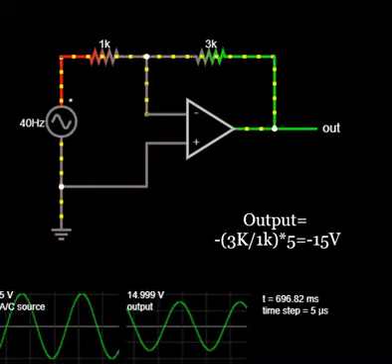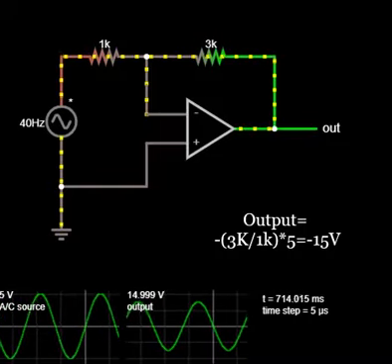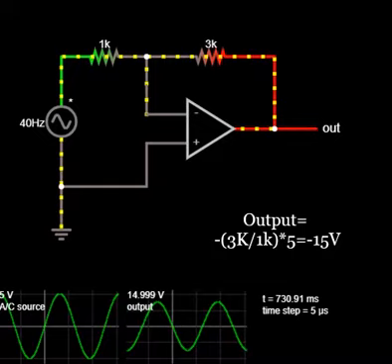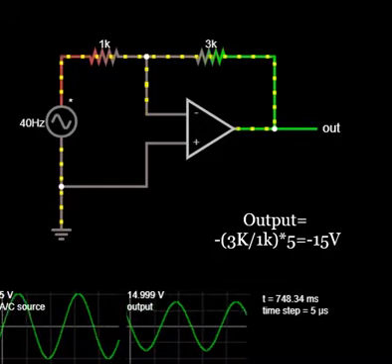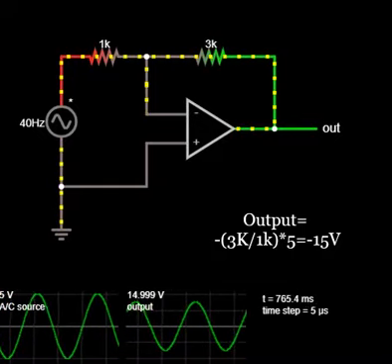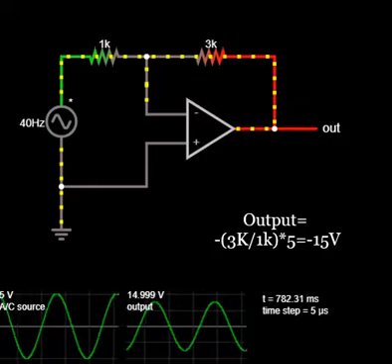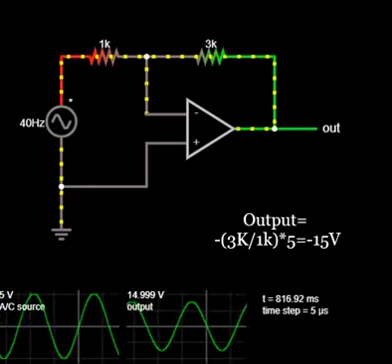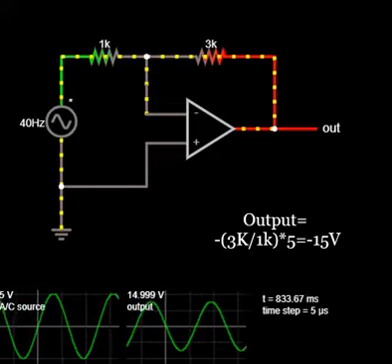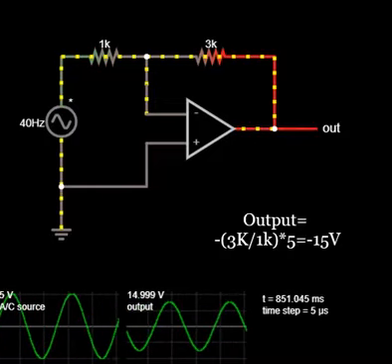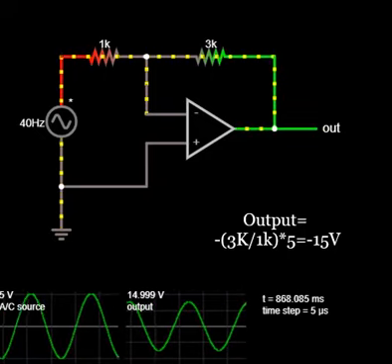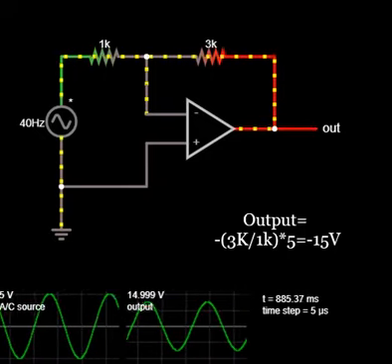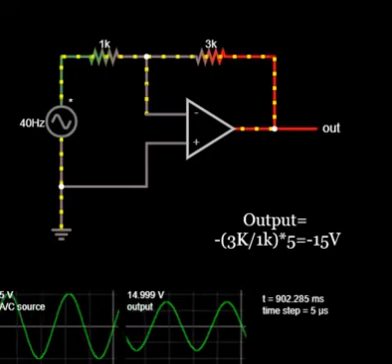So to compute the output voltage, it is computed as resistance in the feedback divided by the resistance which is connected to the inverting terminal, that is 1 kilo, multiplied with the input voltage. And input voltage we have applied it as 5 volt. So that gives me a maximum value of minus 15 because it's an inverting amplifier, so that is why we have a negative sign. So negative sign implies that the output will be inverted with respect to the input.